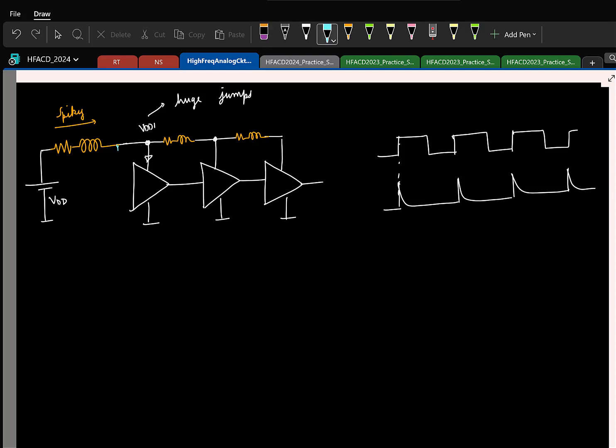So typically this is something you can do. You can go and put a capacitor right next to your circuit, and this is often called the supply bypass capacitor. So those triangular blocks are consuming spiky currents. Correct. One or more of them can consume spiky currents.